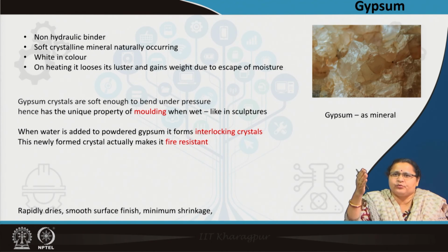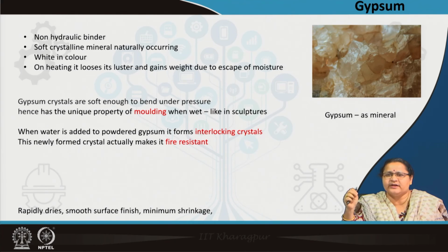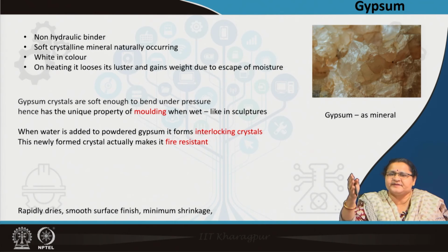So, when we were putting the gypsum board in front of a thermal insulator embedded inside, sometimes the thermal insulator may itself be a fire hazard, maybe inflammable. So, to protect that, the gypsum board is actually acting as a barrier.